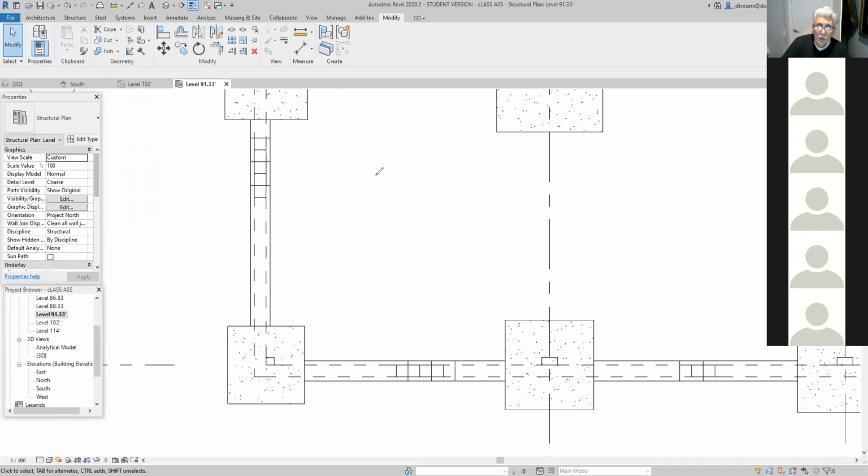Guys, you're going to have to start thinking vertically. What I'm saying is the slab, sir, the slab is 6 inches. So from 92.33, you take off 6 inches. It's not 91.33, is it? In other words, 92.33, that's 92 feet 4 inches minus 6 inches. It would be 91 feet 10 inches. All right, yeah.